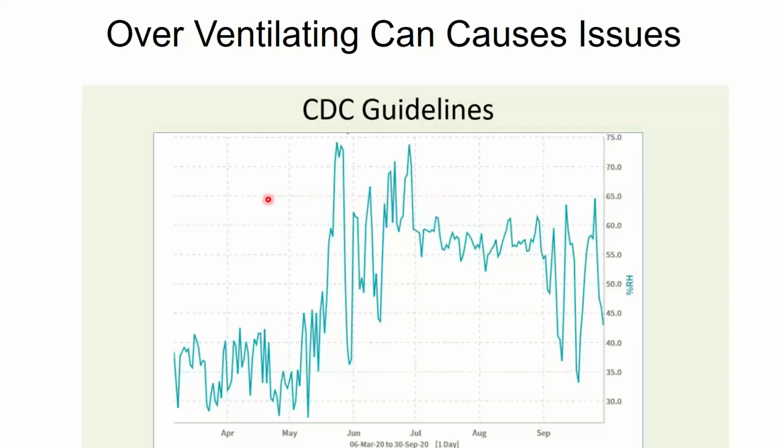If I start getting higher than that, and I forget who told me, I don't know if this is true or not, but enough people have told it to me that it's kind of like a wives' tale, and I sort of believe it: at 70% relative humidity, it'll take about 2 weeks to grow mold, and at 80% relative humidity, it takes about 3 days to grow mold. You keep stuff under 65%, minimal mold growth available.